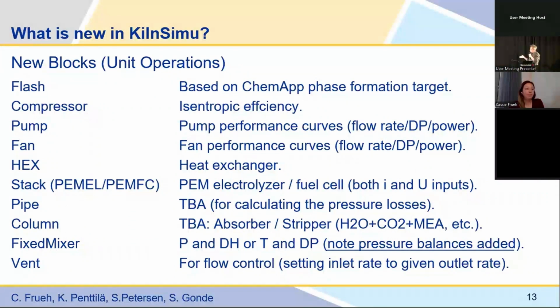And then it can also calculate, using the efficiency, the required power, for example. And then also a model for the pump and fan. Again, it uses these performance curves, and an example one is used. But of course, each equipment has its own performance curves, and then you need to get those and copy paste the values into the table. But that's easy to do.